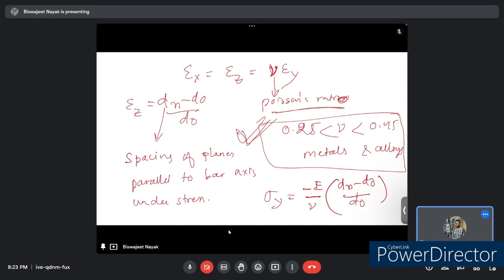So here we can note that only a particular set of grains contribute to a particular hkl reflection, and those grains which are parallel to the surface of the bar and which are compressed by applied stress can only be seen here.